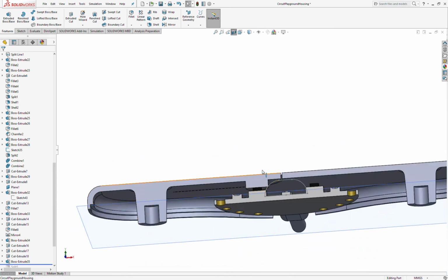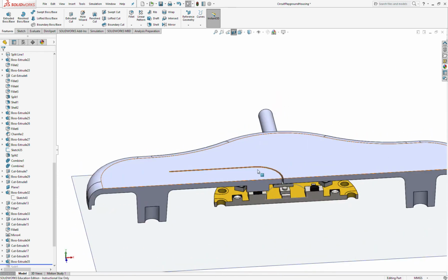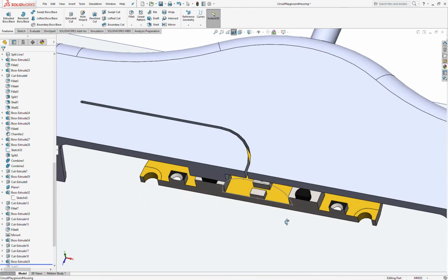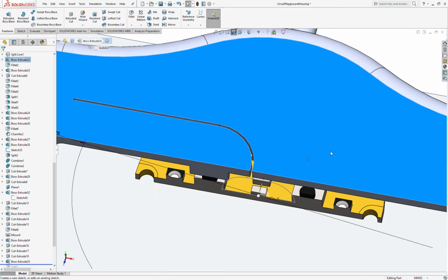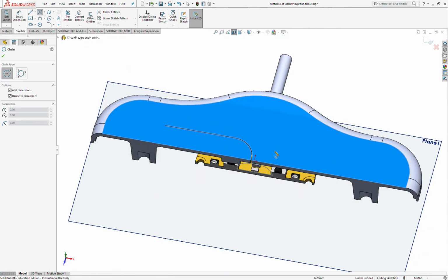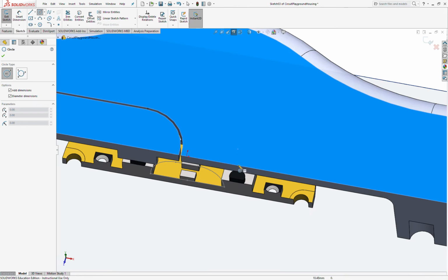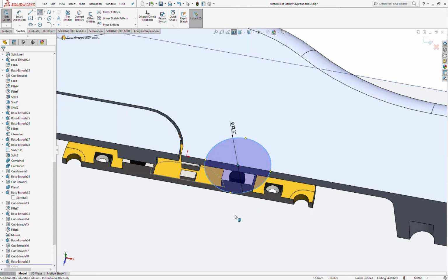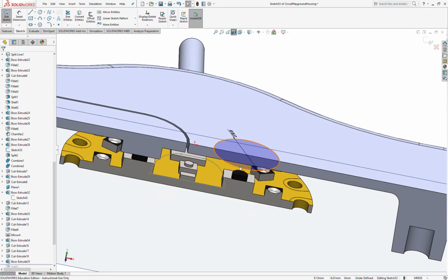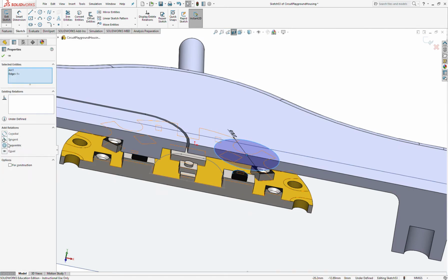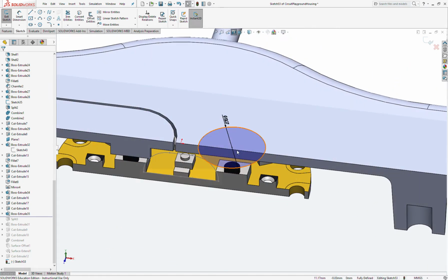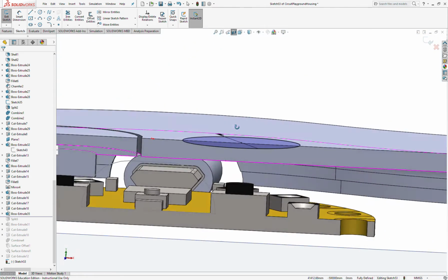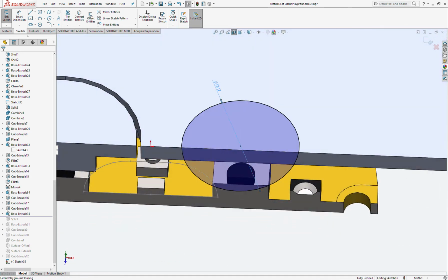So now this piece of plastic will flex. It will press into that button, and we've got a button really easy rather than having to do a separate part. If we wanted to do a separate part though, we could. So we want this to be concentric with that. Doesn't necessarily have to be. It can be offset as long as we are getting that contact, right? And in this case, we're just going to cut a hole.